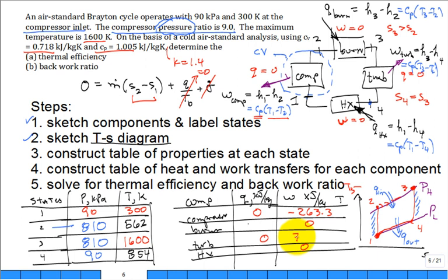And then it's 749.7, and over here in the burner, 1043.2, and negative 556.8. When we do the net Q, we add that column. It's 486.3, and then for the work column, it's 486.3. They match. I'm happy. At least I know it doesn't appear to have an error. I still could have an error, but I know I definitely would have an error if they didn't match.